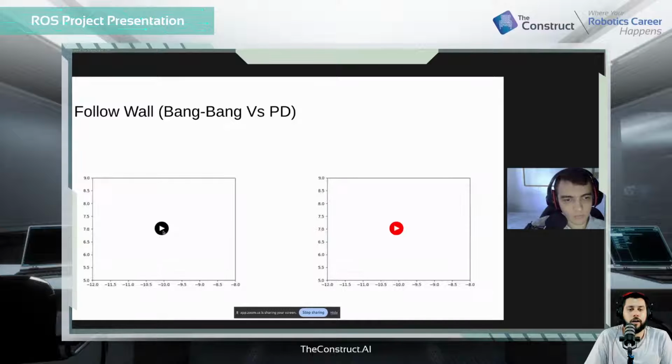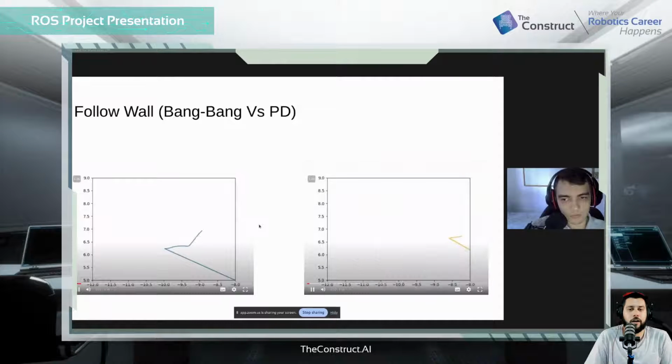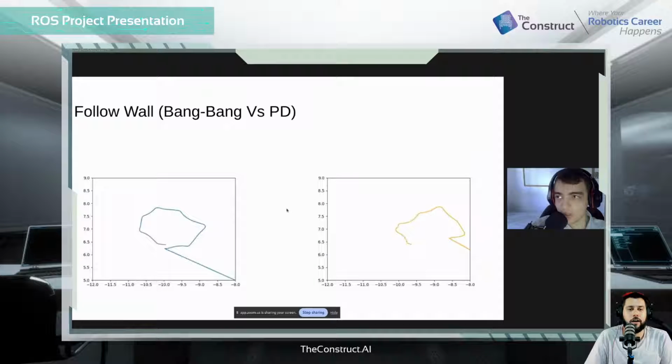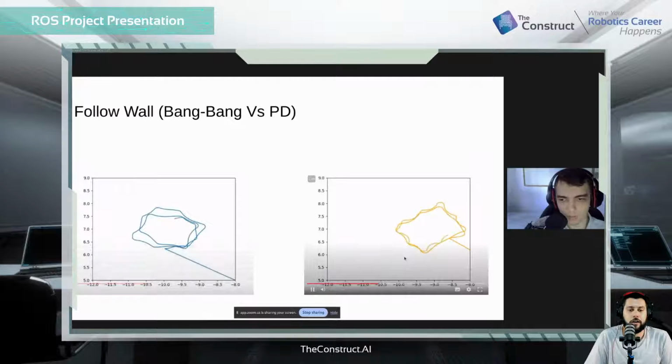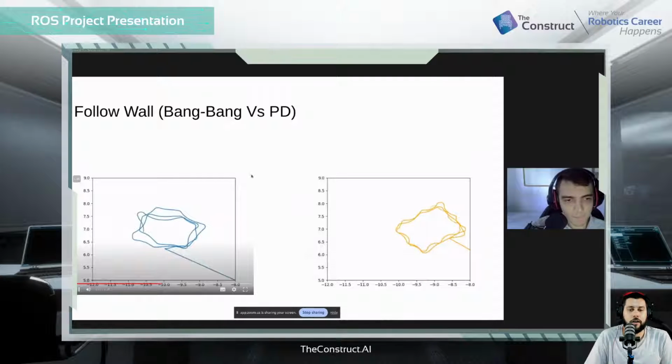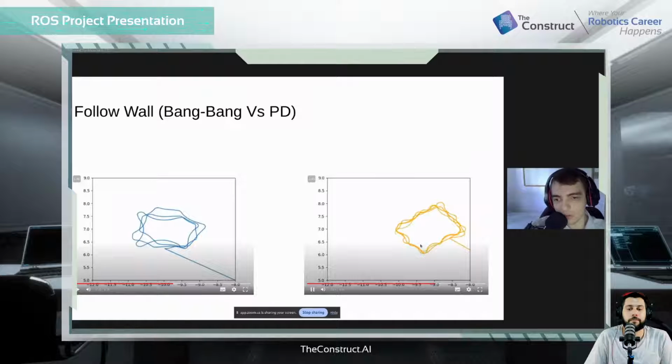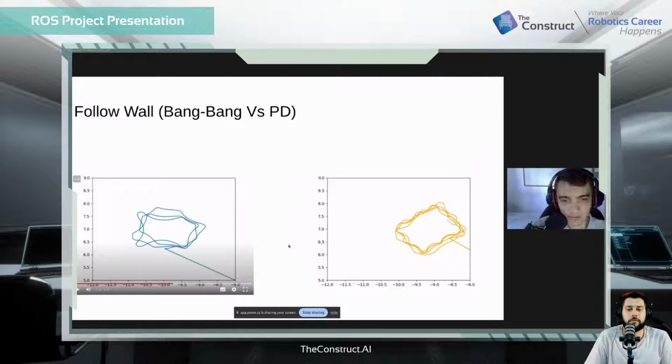in the real robot, but unfortunately, as we all know, the odometry drifts apart, so we don't have a very clean shape. And for some reason, the odometer of this robot has this big discontinuity in the beginning that I don't know why. And of course, I tuned the gains of the controller in the simulation. So when I go to the real robot, it's not as perfect as the simulation. I would need to tune it again.